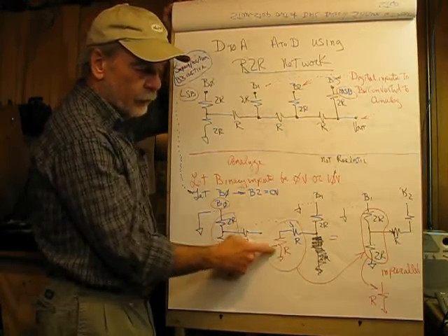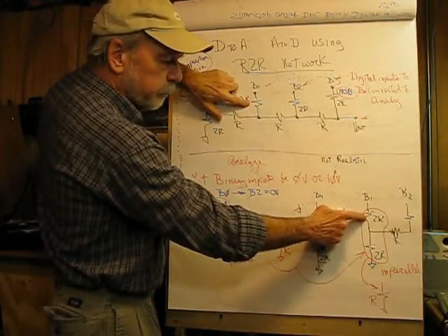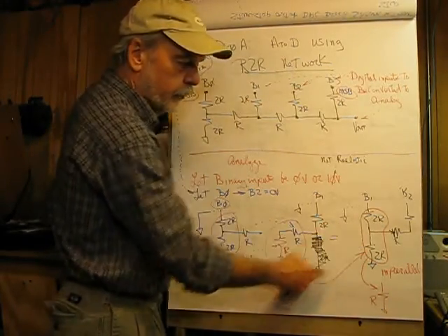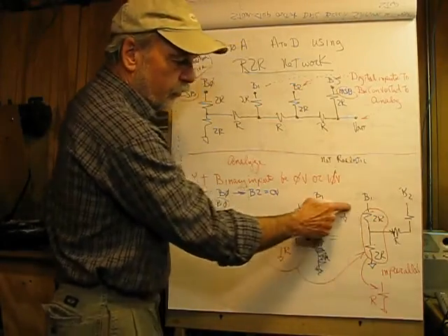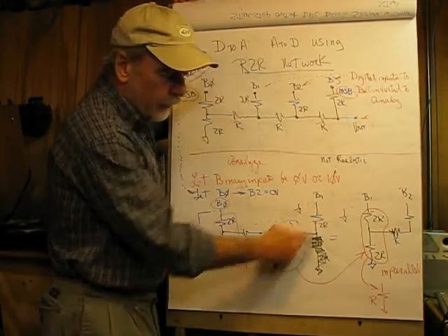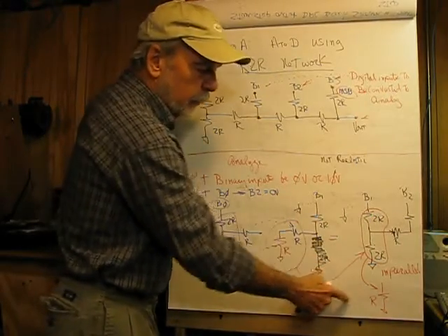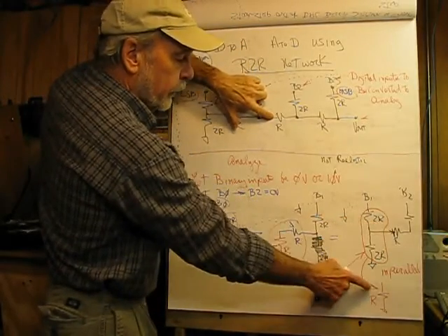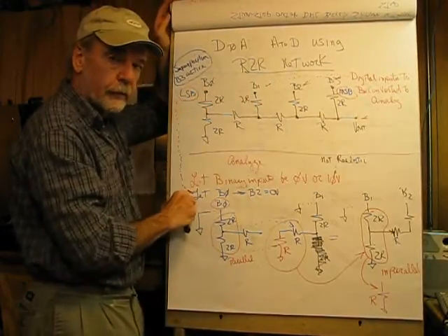So now looking at B1, we have 2R here, and we just collapsed B0 into this. So let's combine these resistors. Here's B1's 2R, and here's the 2R that results from the series combination of this. Again, because B1 is at 0 volts, at ground potential, we can take these 2 in parallel and again come up with an R. So this R corresponds to this guy right here, and this R is everything on this side of the sheet.